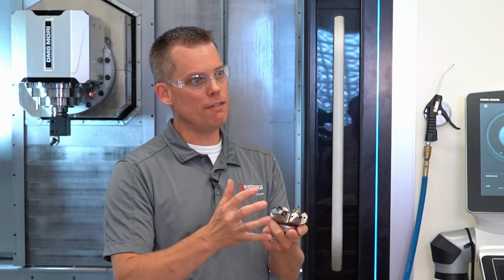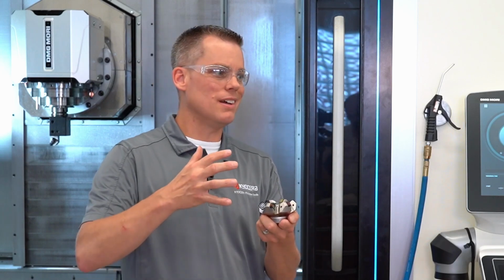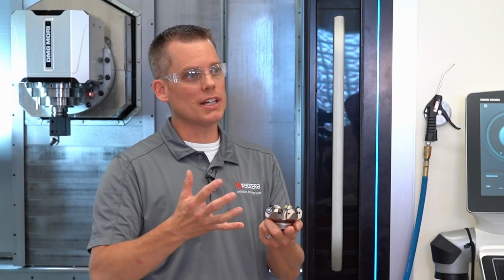They typically can be fed at higher feed rates than 90 degree cutters, further increases economy over a 90 degree cutter, but can't be fed quite as hard as a high feed mill. So they strike an ideal balance in between metal removal rate and economy while still providing a great surface finish.